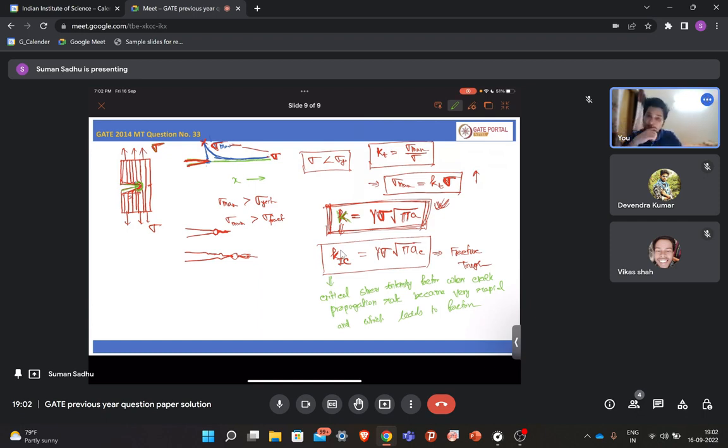So what will be the unit of fracture toughness? Sigma is in Pascal, Newton per meter square you can say, or megapascal. And a is in unit of meter, so root over m. So it will be Newton per meter to the power...